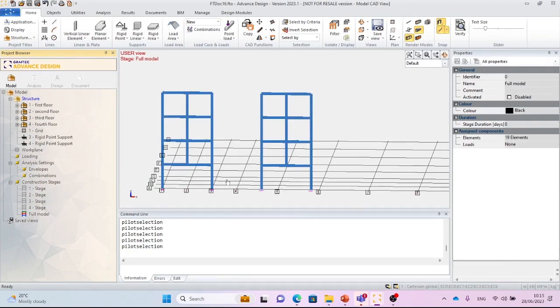In order to perform the analysis and not get any error message, it's important to create a construction phase for this frame, but we will ask all the structural elements to be created on the same phase. So this is the little trick in order to bypass any errors or warnings coming from the software. Because as long as you have enabled the construction phases, everything within the model needs to belong to some construction phases. Either you have multiple construction phases or just one for all elements.